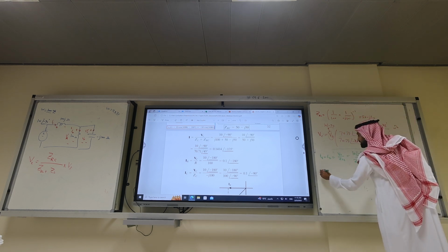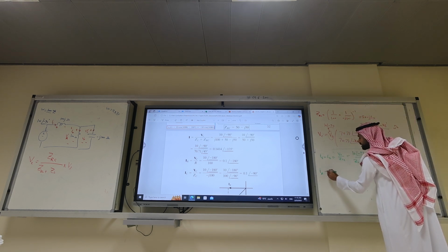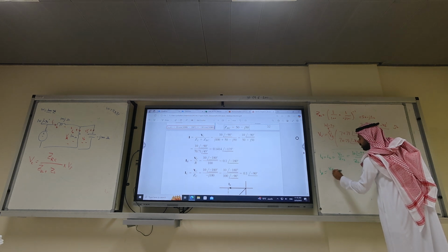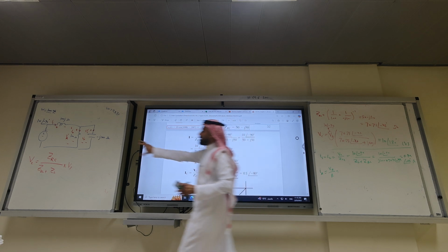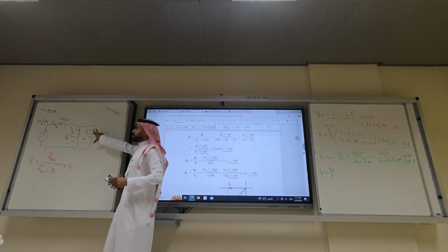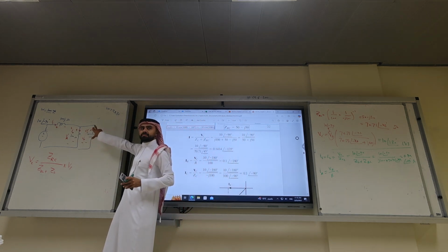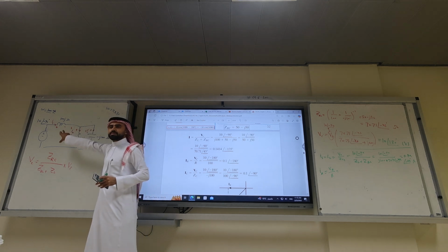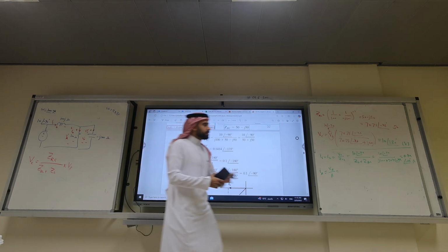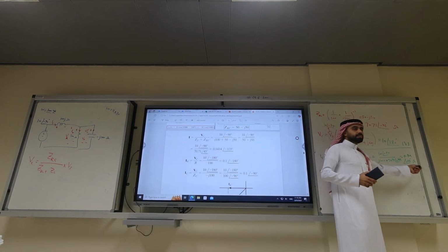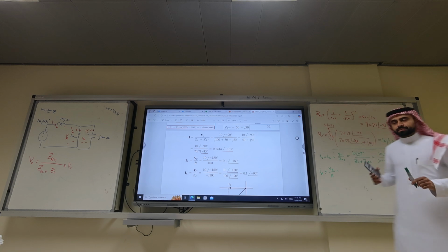Now, what is I sub R? I sub R is actually VR over R. But VR is in parallel with VC, so it is VC. Get it? Did you get that number? Same? Try to get it.